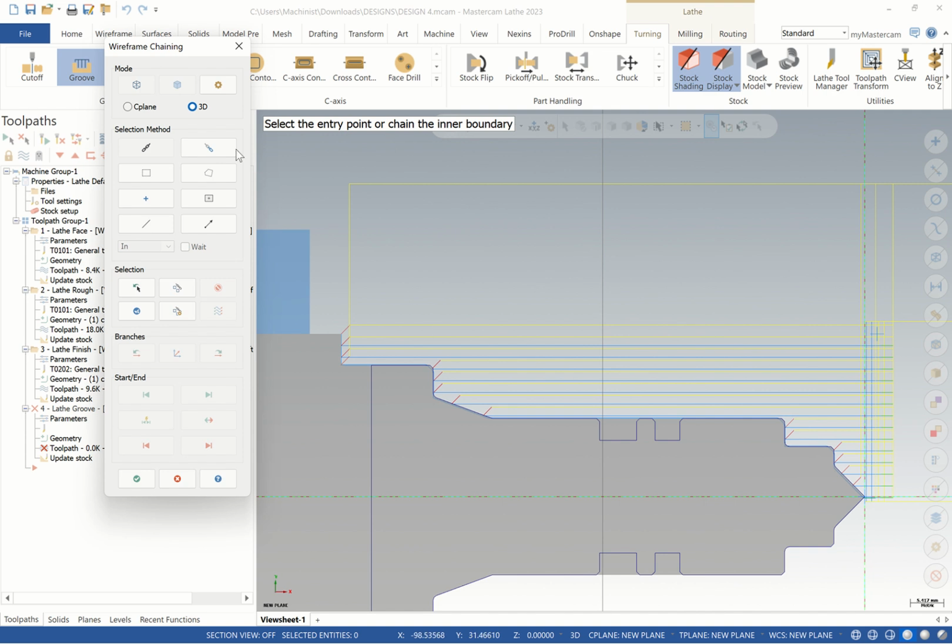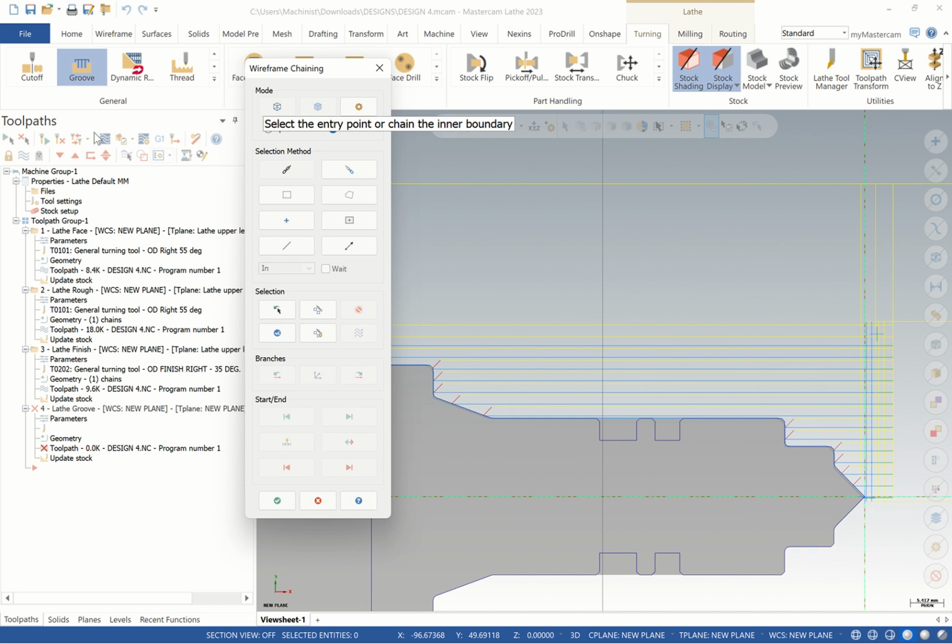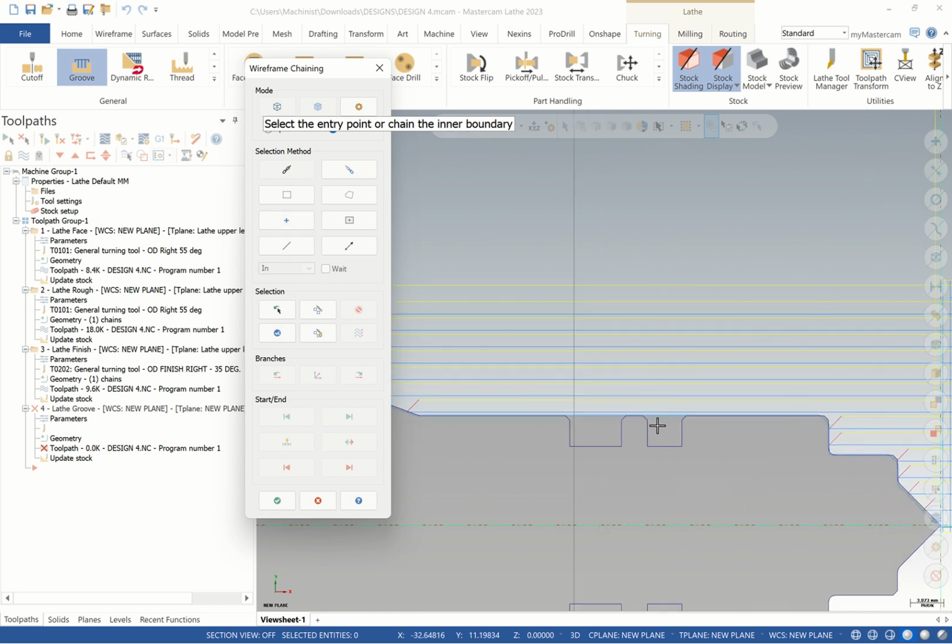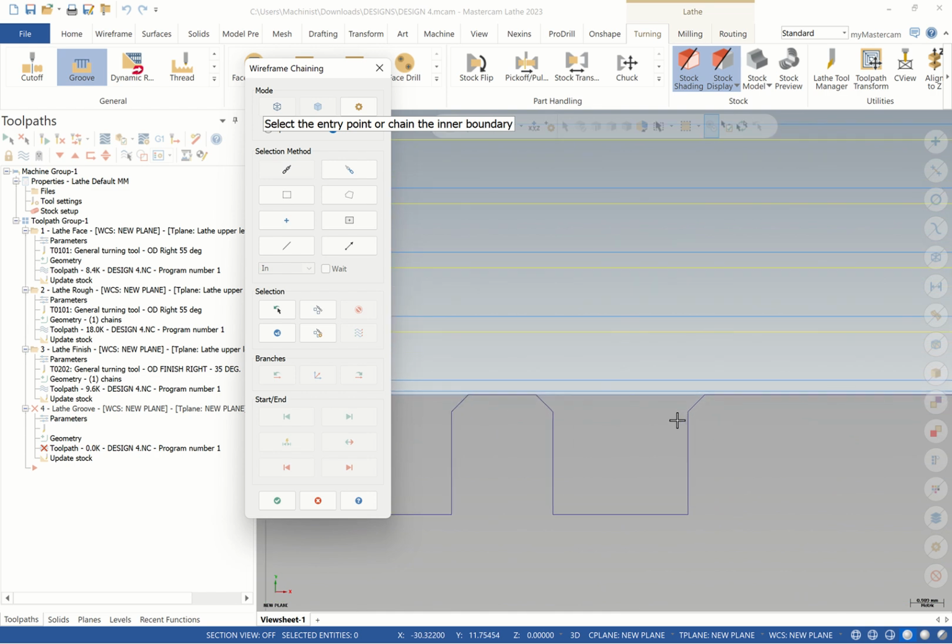In case you see this tool profile, too many of them, what you do, you can just hide. Before I do hide, let me go to that one. So I can pick the profile. I can expand here. For example, I can pick here. Then I can say reverse.